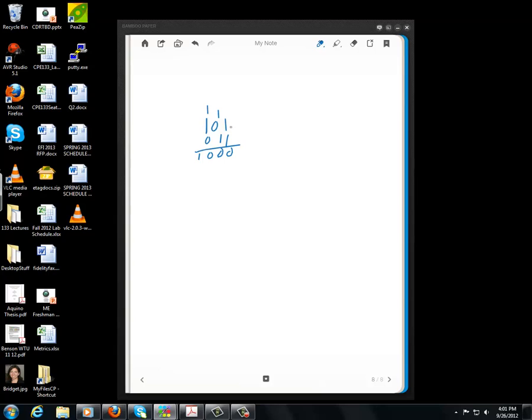And what we did to do that was we started off with a half adder because we had two inputs, and then we needed two full adders afterwards. So in order to add a 3-bit number, we required one half adder and two full adders to make that happen.